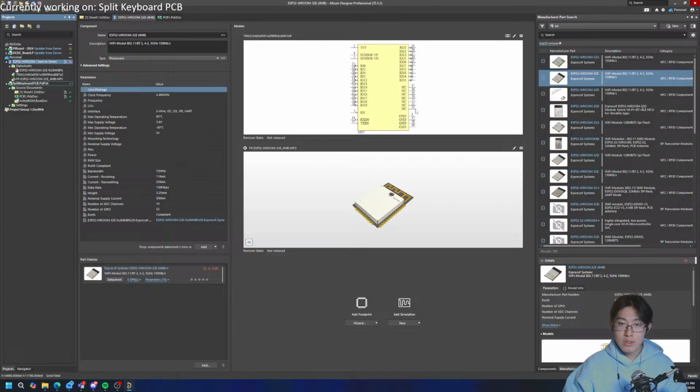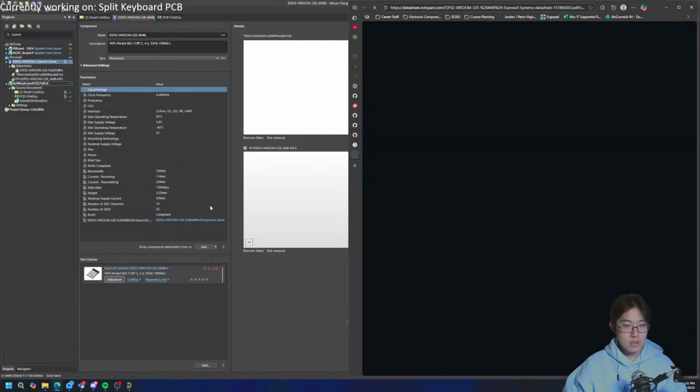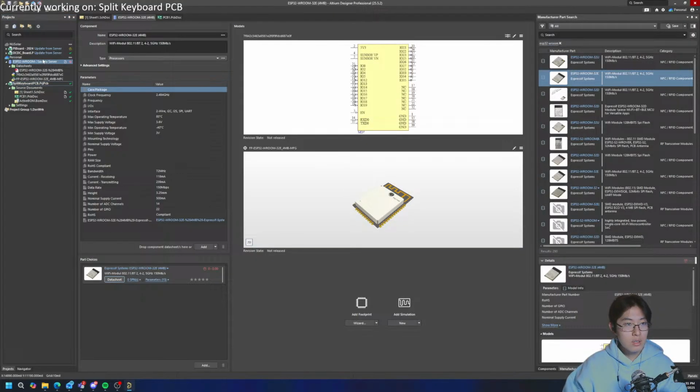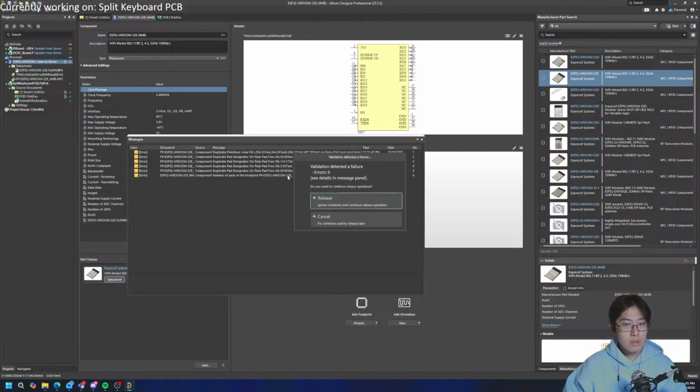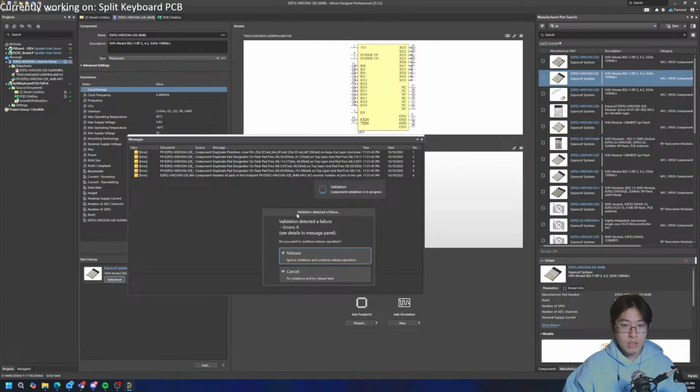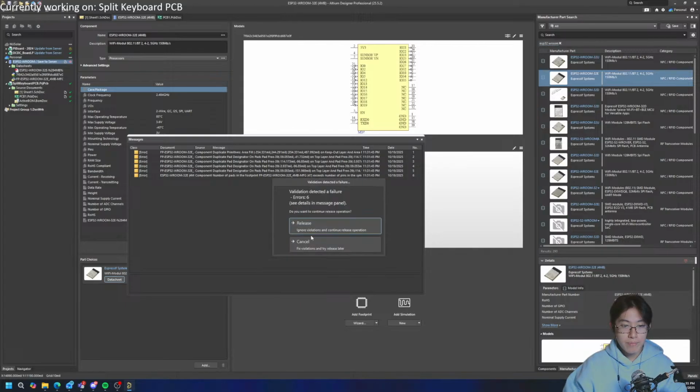Why are 17, 18, 19, all of those no connection? I feel like those should be... Huh. That's odd. And then IO 1 and 3 are the RxD and TXD. That's fine. Okay. Sensor VP, sensor VN. What are these pins? I gotta look at the datasheet. Okay, but for now we can save this to server, I think. Component duplicator designator. Yeah, it's fine.